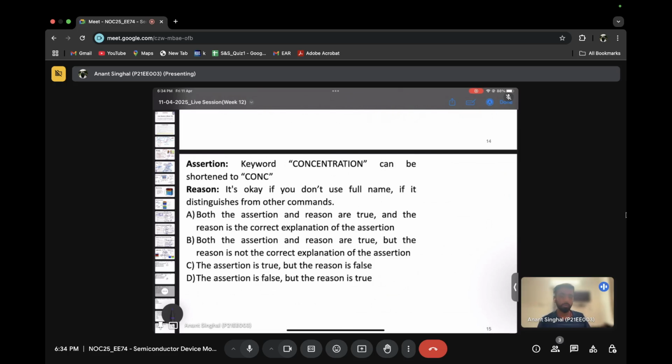In that script, you need to see how exactly the script works. In SDE you are designing the device, and this is transferred into a script known as the SDE file, in which you define the doping of each region, that this box is silicon, and the XY coordinates of the position. The screenshot which I showed you was the Sdevice file.